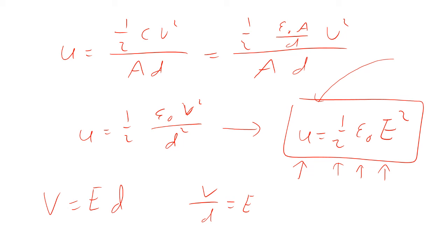The problem is, if you're not careful, blowing all the grain around causes triboelectrification, that is, frictional charging, so you get electric charge. If the grain elevator has a metal framework, you create a big capacitor. If the electric field gets big enough, it can start making electric current flow.